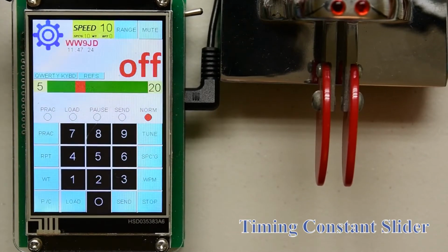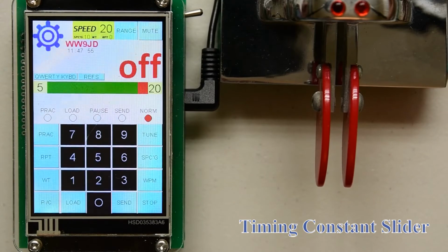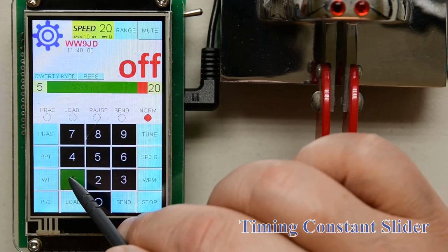It's pretty darn close. Now I've reset the keyer to 20 words per minute with 10 word per minute spacing Farnsworth, and I'll resend the number 10 Paris file to see how close that is.